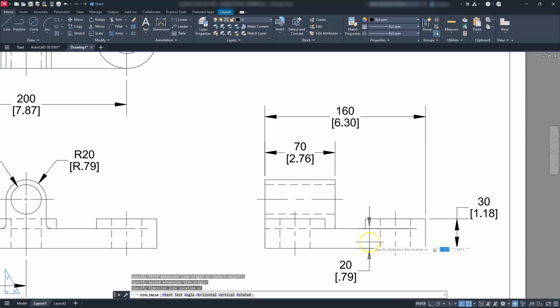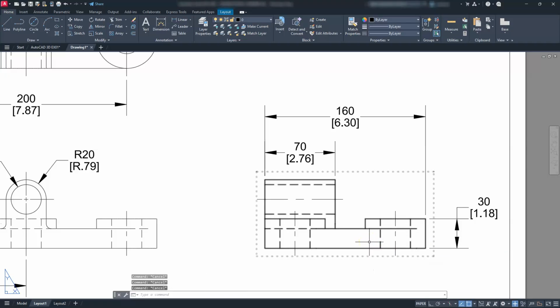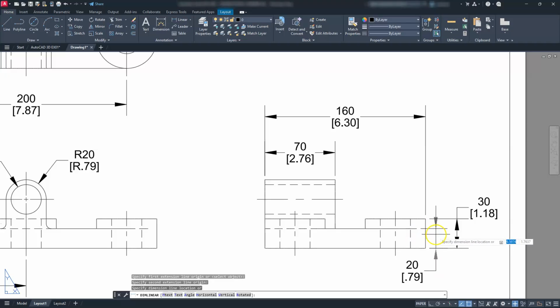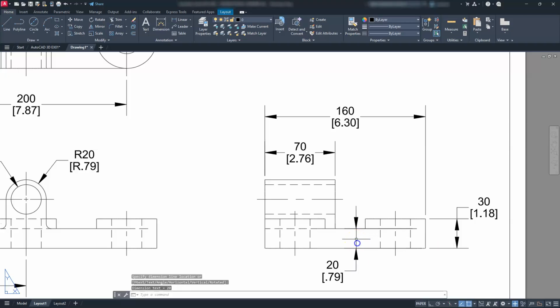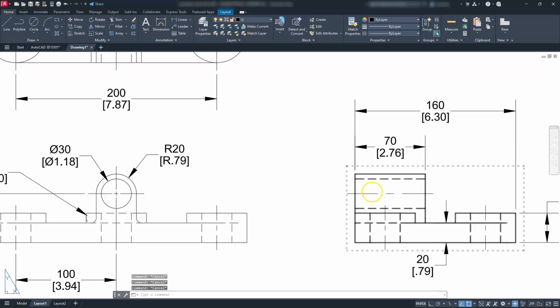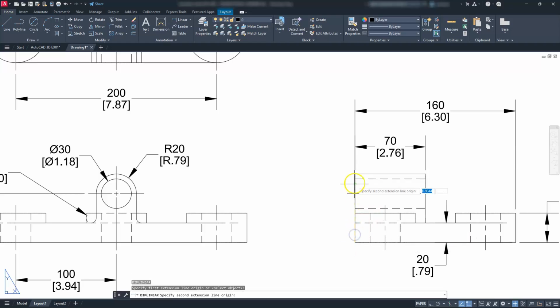this way. You know what? Let's change that. And I'm going to put that dimension. Might be kind of hard to see over here because I really can't dimension to a hidden line. Yeah, I'm kind of stuck with placing it here. I don't like it, but yeah, let's place it there. I think it looks a little neater there. And then we have a couple more dimensions here, right? So put a linear dimension here.